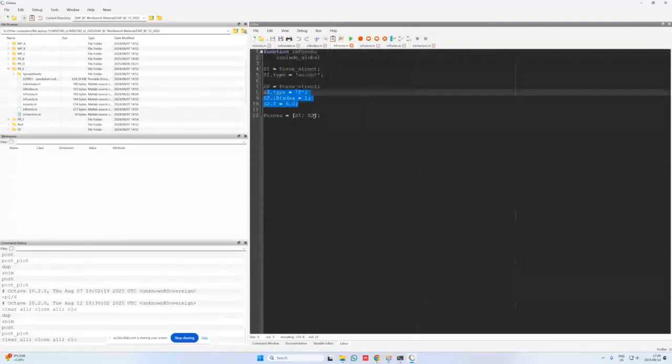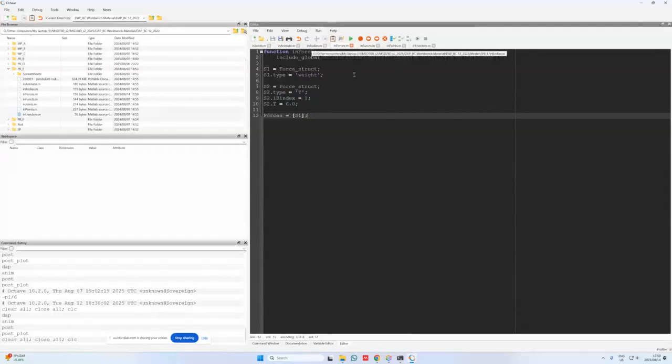switch off the torques. So to do this, I can actually just go and remove S2 over here. So now we're not applying any constant torque to the system. We only want to see what the effect is going to be of the driver constraint. So if we specify now a constant angular acceleration on the pendulum rod, what will happen to the system?